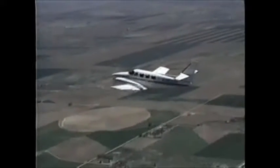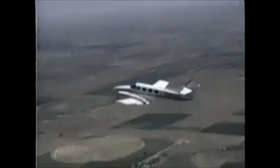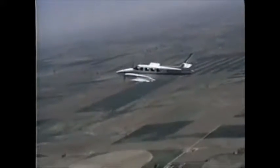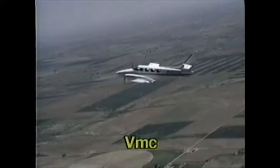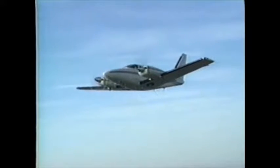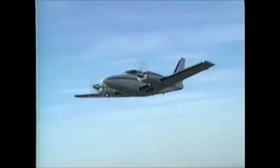Regardless of the type of airplane, as you slow it down, you reach a point where the rudder can no longer counteract the yawing tendency. At this point, called VMC, the airplane will become uncontrollable unless you take immediate action. Each multi-engine airplane has a VMC that's established under a specific set of conditions.